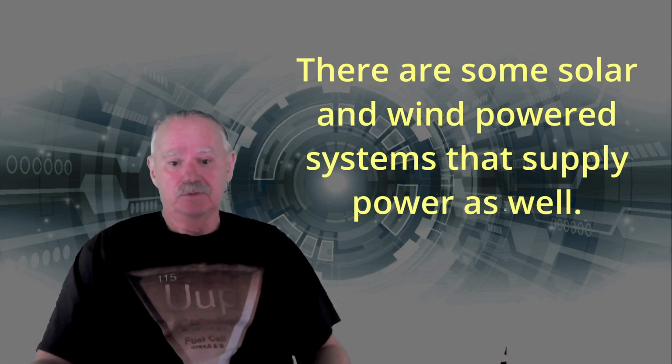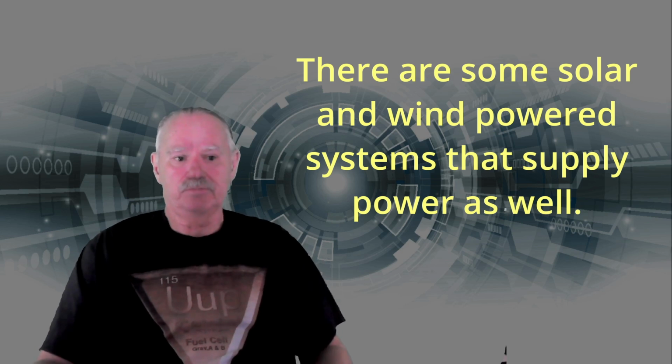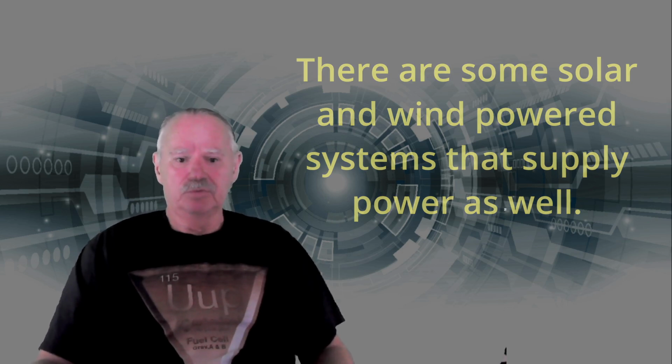Most homes have a 200 amp breaker panel coming in from the outside, and it is then subdivided into smaller breakers. Most of them you will see are in the 20 amp range. There are 110 volt, 120 volt breakers, and there are 220 volt and 240 volt breakers.